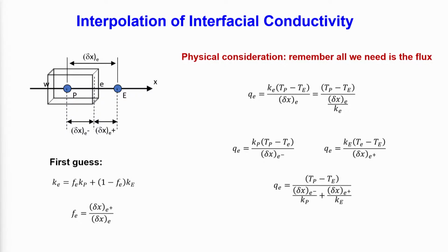So in the discretization equation you have seen that we require the thermal conductivity at small e and small w, but usually for a problem when you describe, the properties or any input they are given at the main node points, capital P, capital E, etc., not those small e and small w. So you have to interpolate.